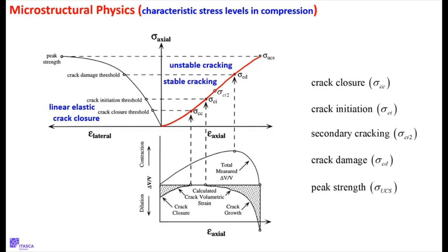And so that's something to be thought of. To minimize that effect experimentally, you try to make the platens farther away. Like if you had a giant long thing, no matter what's happening, if it's 10 times longer than the diameter, you don't really care about what's happening far away at the platens. It doesn't really matter. But as you make this thing smaller, if the diameter is the same as the height, then that platen effect is going to have a big effect.